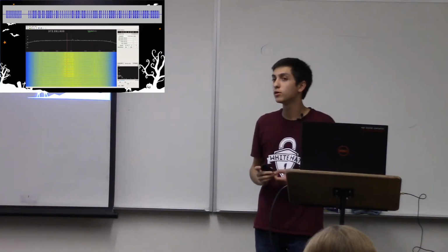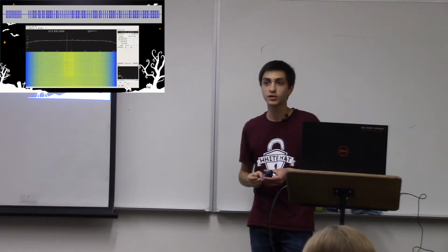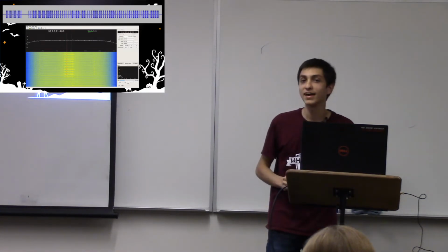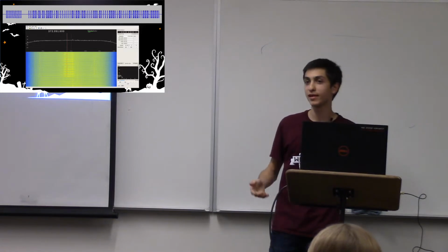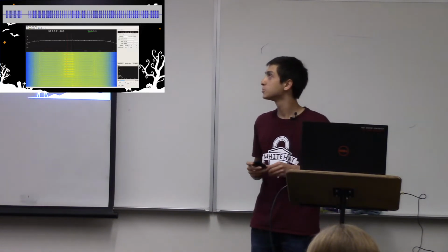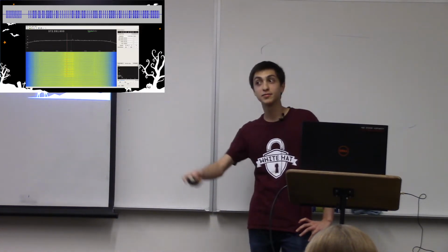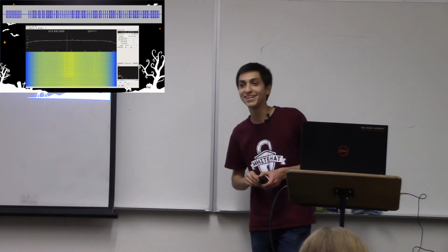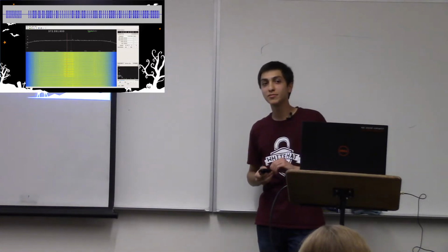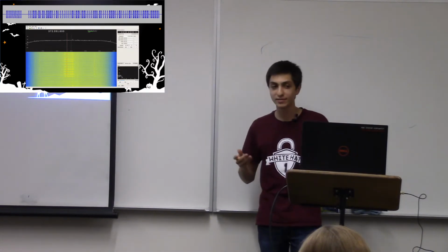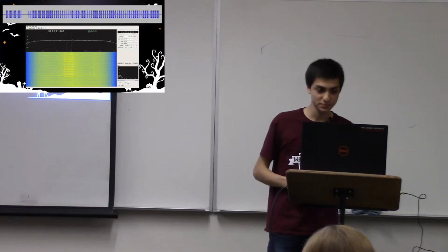But what if we were to replay that same signal from another device? Would the garage door still open? Yes. So that's called a replay attack, where you capture a signal and replay it. So what's pretty cool about this is, say I'm driving home, and then I open my garage, and some guy in the bushes, with this SDR, records that signal. Well, at a later time, he could come and replay that signal from some other hardware and get into my garage without actually physically having this little device.